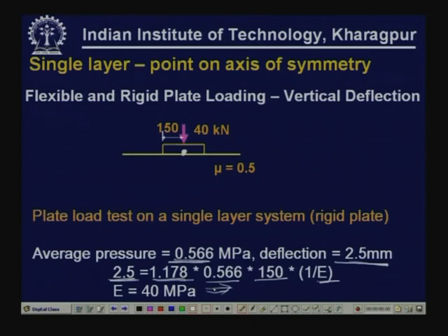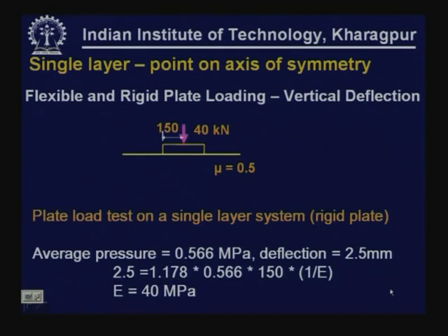So, this is a very convenient system, though not very rational, because this is a very static load, loading time is very large, but still we can get some idea about the elastic modulus value of a single layer system, provided we have a single layer system. We can conduct a plate load test on that, and using the expression for surface deflection, we can work out the modulus value of the elastic layer system.